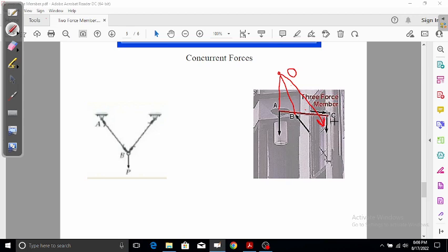This is the resultant of the pin. This is the resultant of this reinforcing bar, which is reinforcing the bracket not to bend, and then the weight, which is going to be vertically downwards. We can basically extrapolate it backward, and they're all converging to point O. So this is another example of a three-force member. I hope you have understood what really is a three-force member.